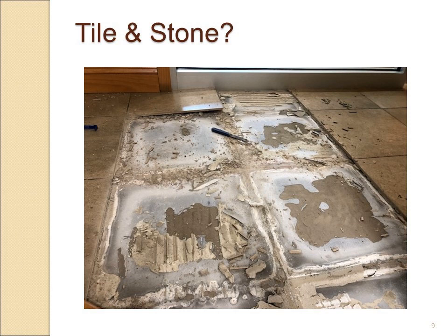Well, absolutely there could be a failure with a tile and stone assembly. As we see here in this picture, the tile itself isn't damaged, the mortar isn't damaged, but yet due to the excessive amount of moisture, that moisture caused a condition such as efflorescence that is expansive, and this efflorescence caused a failure with the tile. So we can see that moisture can affect the assembly of the tile, and we'll talk a little bit later about the tile and stone themselves, if we don't consider them.